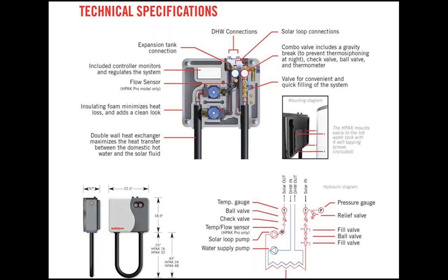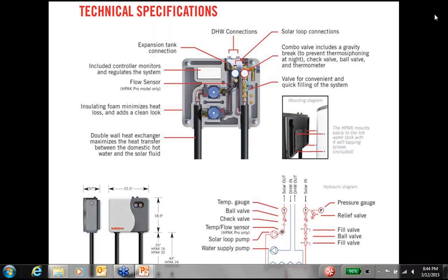I did have a problem. One of these joints in here had an ever so slow leak because they were Loctiting these fittings, and they didn't Loctite this fitting. The water slowly evaporated over, I think it was 5 years, and the pressure slowly dropped. The guy called up and said, hey, I don't have any hot water. I went on, and it's because there's no pressure, so the pump doesn't work. And so I had to go fix that.